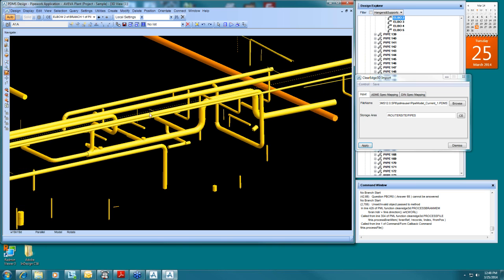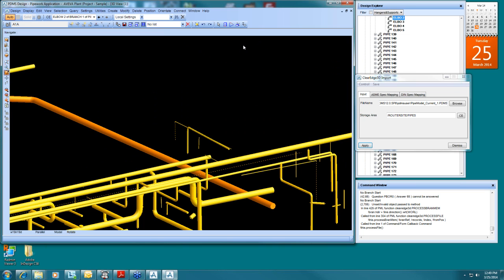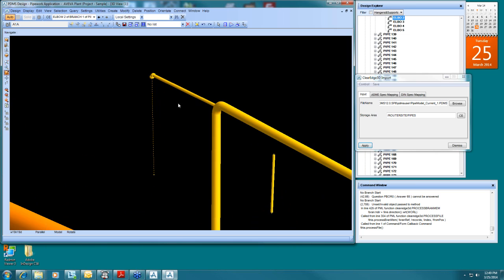And that is primarily due to the accuracy of the scan and the fact that if you have an elbow like that, which is a socket weld elbow, that if the pipe is deflected or bent or something like that, the elbow can't take up the angle because it's a fixed 90-degree angle. In most cases, like for butt weld piping, these elbows will have a variable angle on them so that it will adjust to the angle of deflection of the pipe.